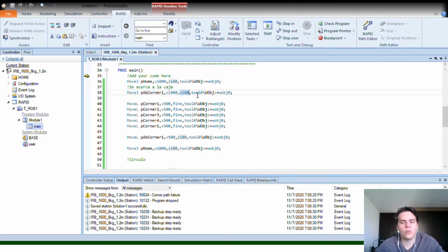When going from one type of movement to another, the simulation creates like a small sphere of size, in this case 100, and if the tool point of the robot passes through that zone, it's going to start to deflect to the next movement, making the transitions between movements more natural or softer.